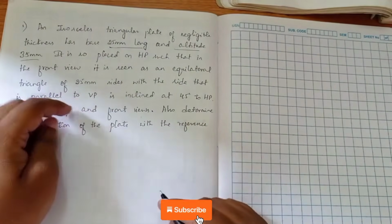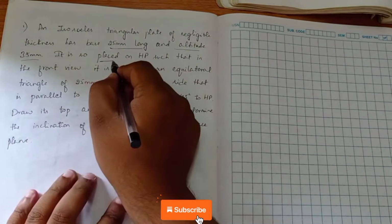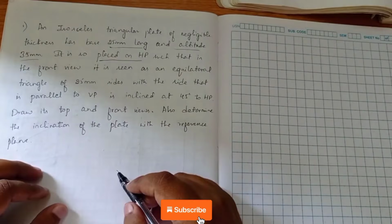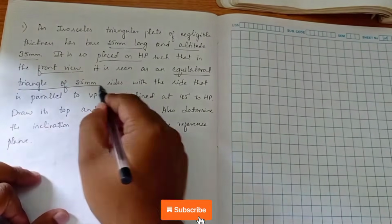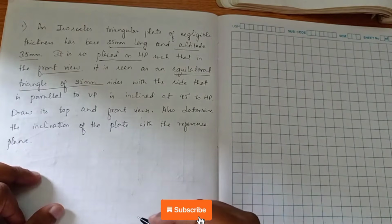Now before construction, it is so placed on HP such that in the front view it is seen as an equilateral triangle of 25 mm side. So it's telling that it will be placed on HP, but in the front view we have to get an equilateral triangle of dimension 25.